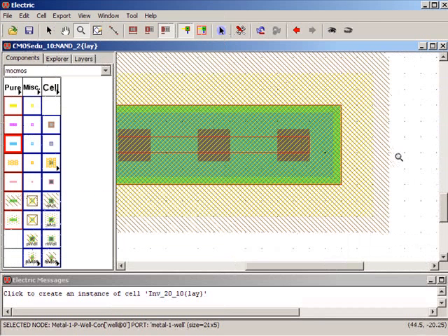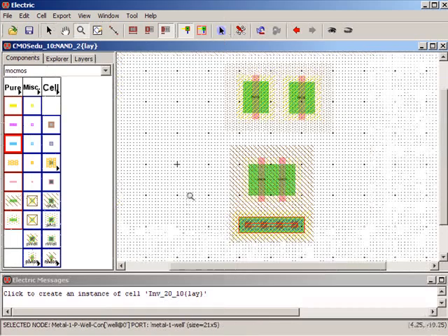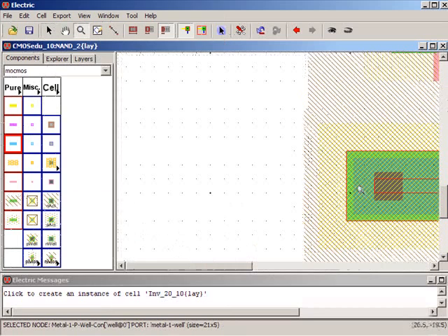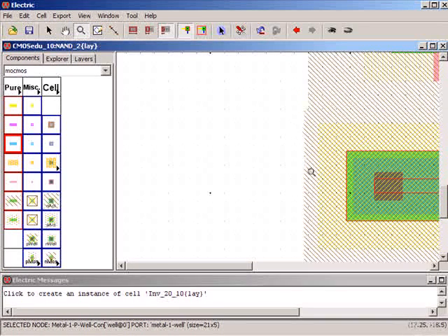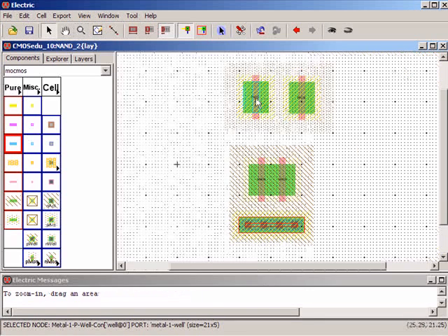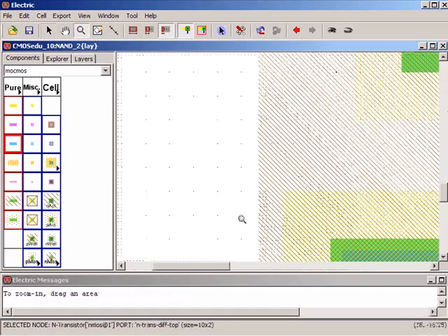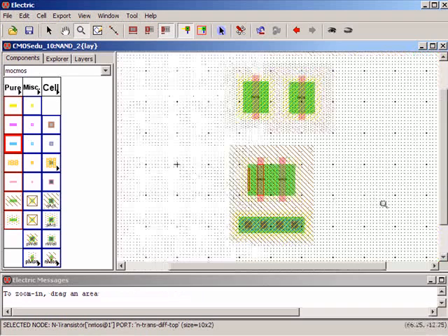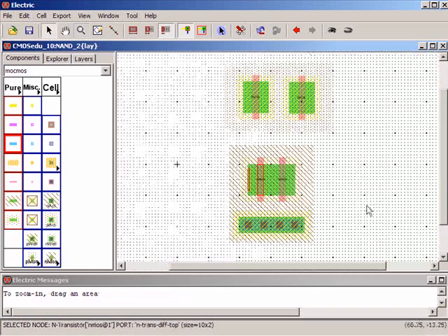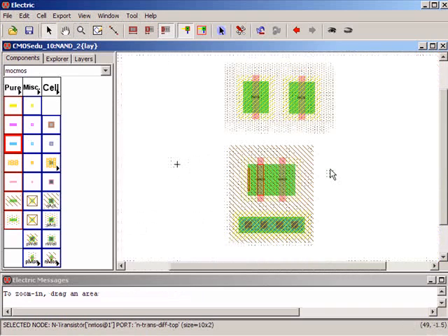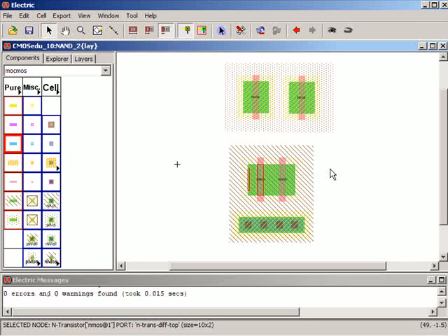Okay. Fit. Zoom. Yeah, it looks like we need to go 20.75 to line everything up. Or, you know what we can do instead? Is we can hit fit. Move this over a little bit. Zoom down in, and it's all lined up. Turn the grid off. Do a DRC. We might have an error down there. Nope.